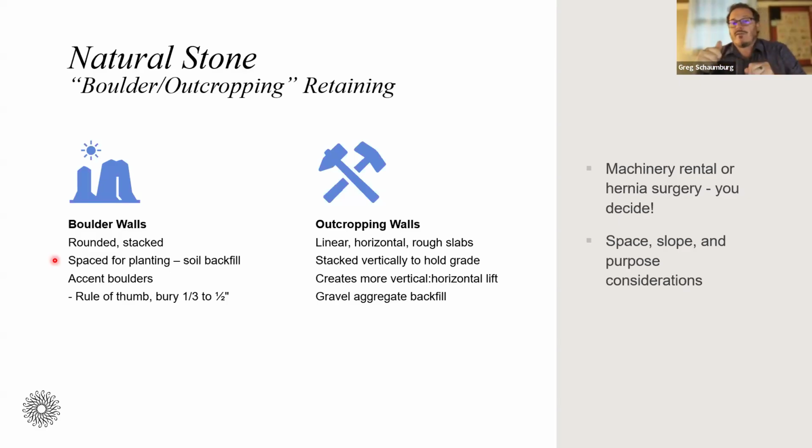So the rule of thumb for that would say bury a third to a half of the boulder in the actual backfill, and let a third to a half project outwards from the ground level. So you're actually anchoring a lot of the material in the ground with it.